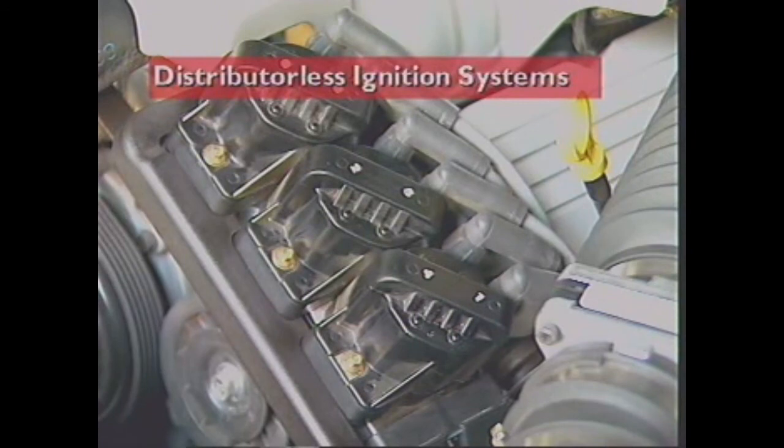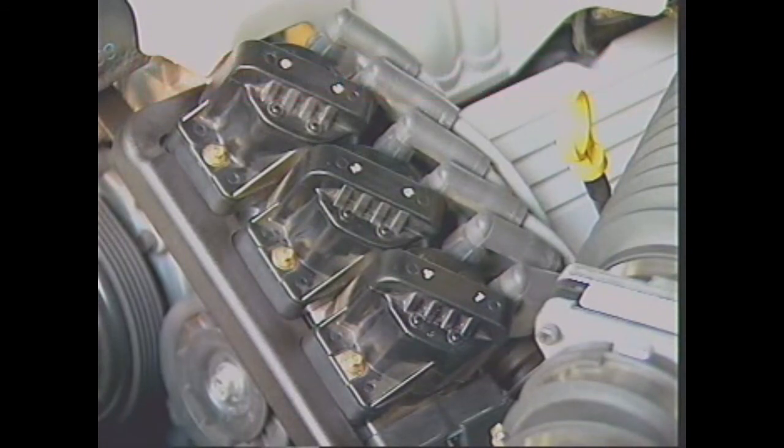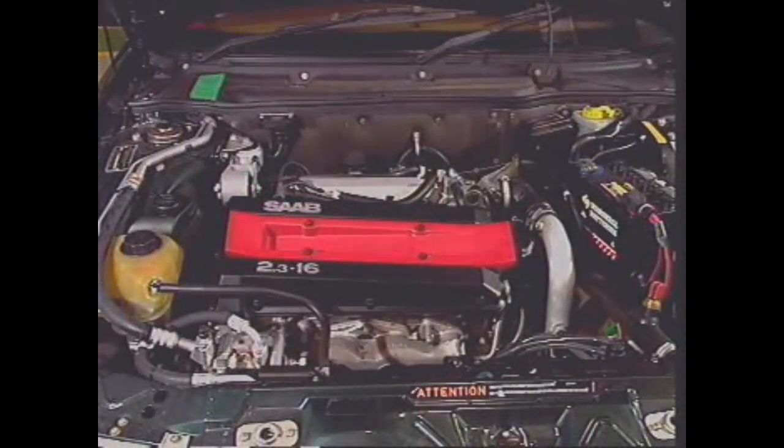In systems of this type, the distributor is eliminated and each spark plug is fired by a high voltage impulse from an ignition coil shared with a companion cylinder, or by an individual coil specifically for that cylinder. This is referred to as direct fire ignition. In a waste spark system for a 6-cylinder engine, 3 ignition coils, each with their own primary and secondary windings, are combined to form one coil pack.